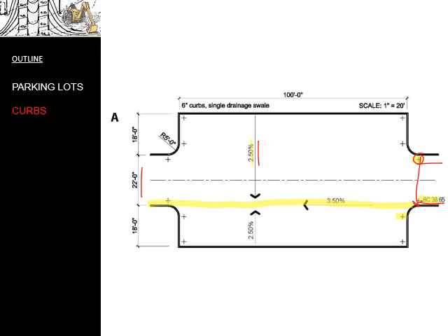The next spot is just a little more complicated because it requires two calculations. First, it requires a calculation to find the spot elevation that is 5 feet away from your given spot elevation. To do that, you're going to use this slope, and you know it's 5 feet away because we've given you the radius of 5 feet.